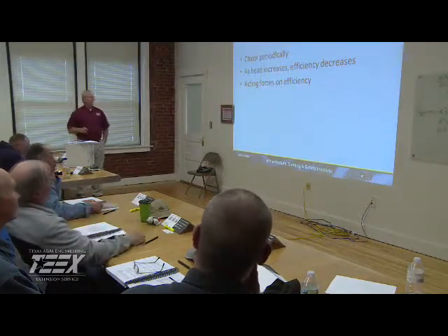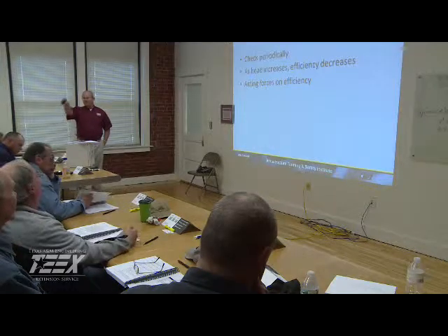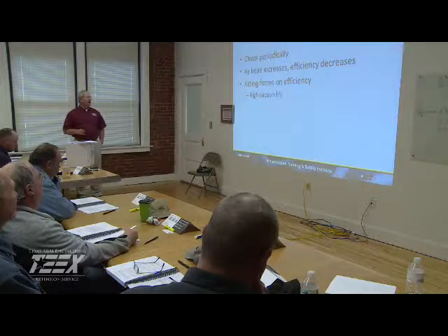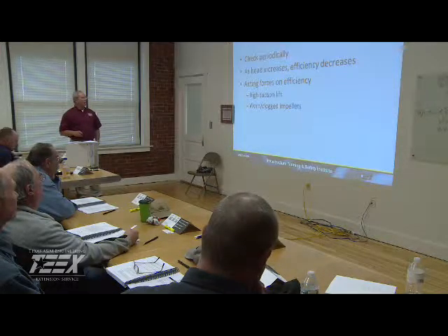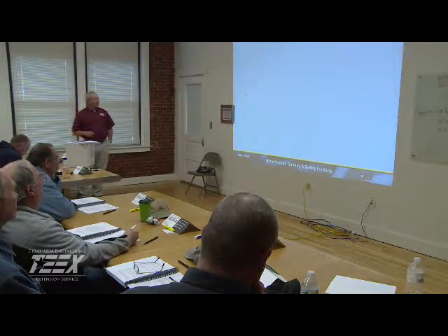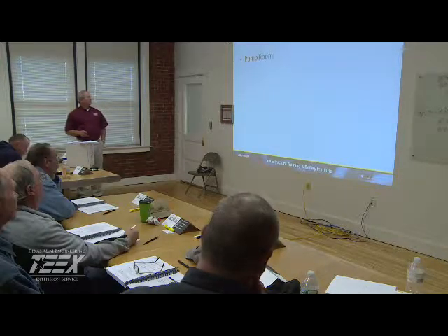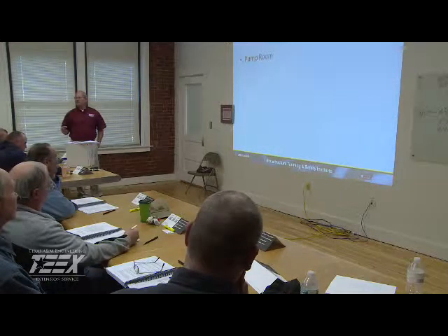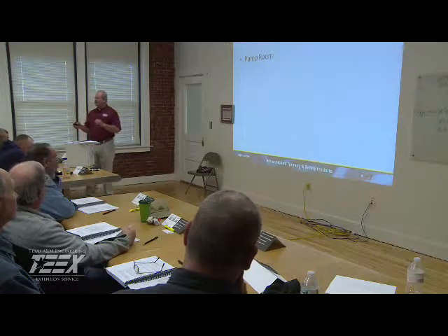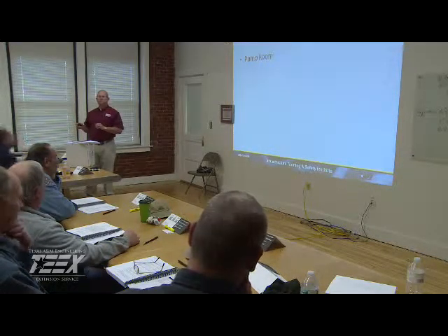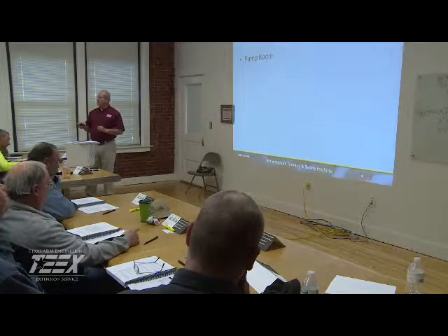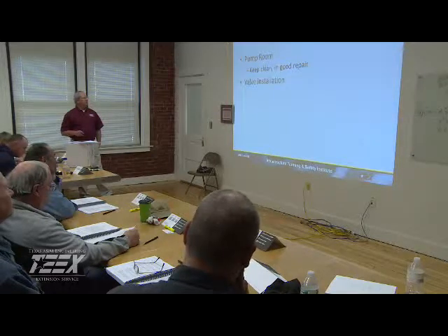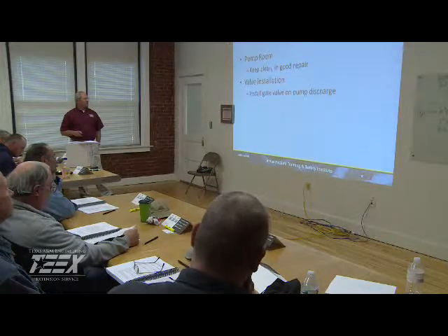Factors acting on efficiency, remember, that tuberculation in that pipe can cause additional head, right? High suction lift, worn clogged impellers, high discharge head, all of those things. Pump room, remember, this is where the pumps are housed. Motors, if you can keep that pump room cool, the more efficiently that motor will run. Remember, it does not like heat. Keep it clean, in good repair, with very good valve installation.